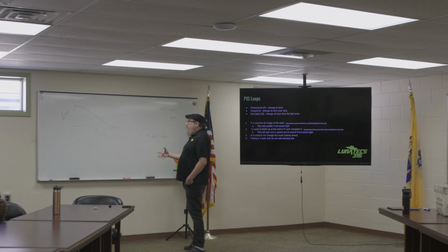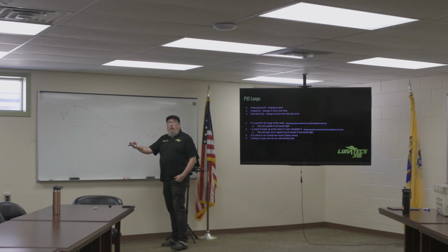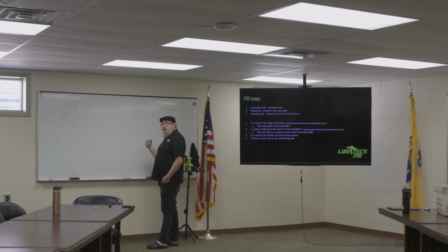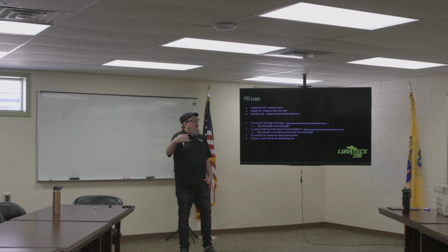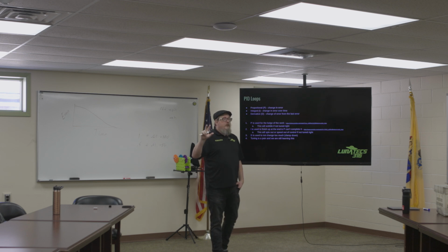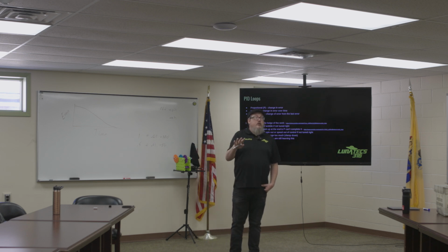Okay? So now my car speeds up. It's 100% power to the wheels. I take another measurement. I'm now at 50 miles an hour. I times it by 0.01. What's that value? 0.5. So when I get to 50 miles an hour, I'm going to start slowing down the car. I'm going to say, hey, only give the engine 50% power. Does that make sense?